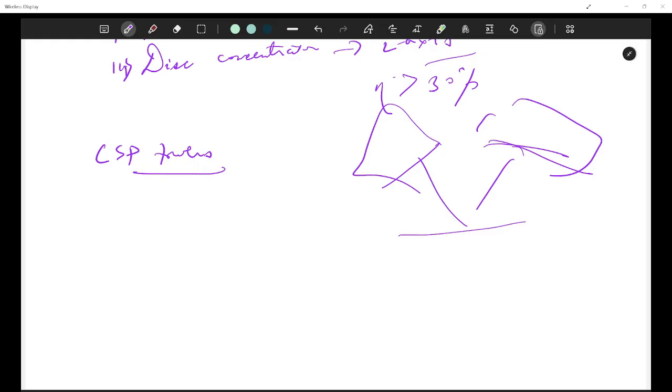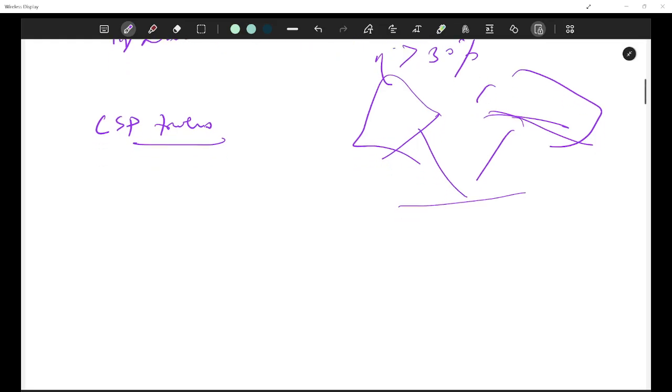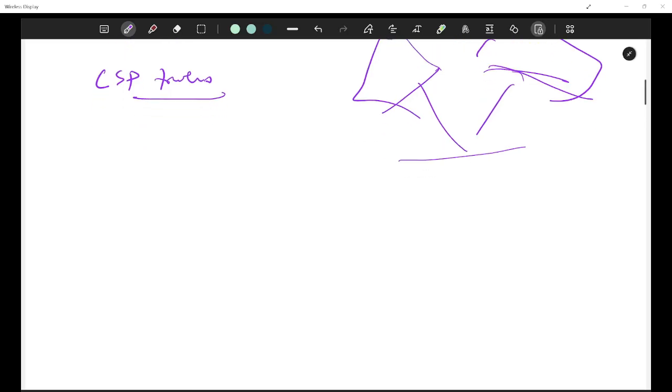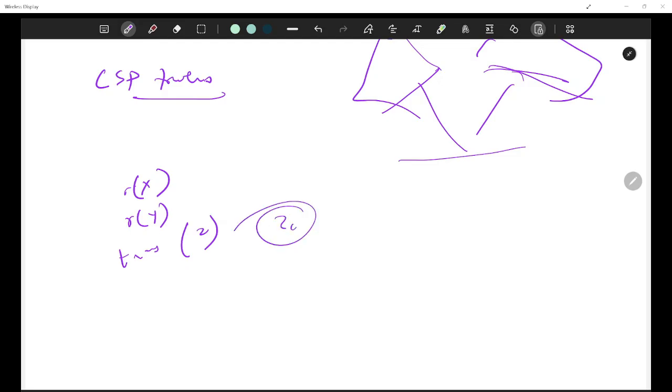All right. Then when we saw this RPS parallel manipulator, it basically provides rotation about X, rotation about Y, and translation along Z. One actuator is redundant and it imposes a constraint that we have to keep ZC constant. The kinematics of 3 RPS is something that we have already seen.